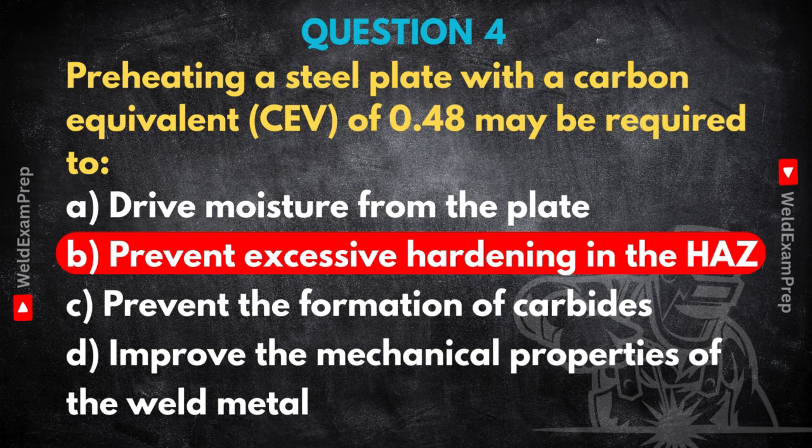And inspectors have standard methods. Temperature indicating crayons are very common. They look like wax crayons, but melt at specific calibrated temperatures. Oh, okay. Temp sticks. Exactly. Or they might use visual contact thermometers, thermocouples, sometimes even non-contact pyrometers.